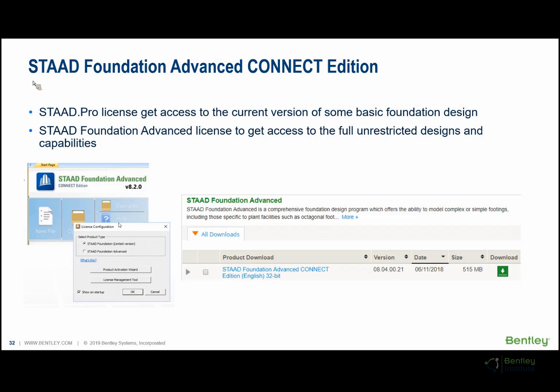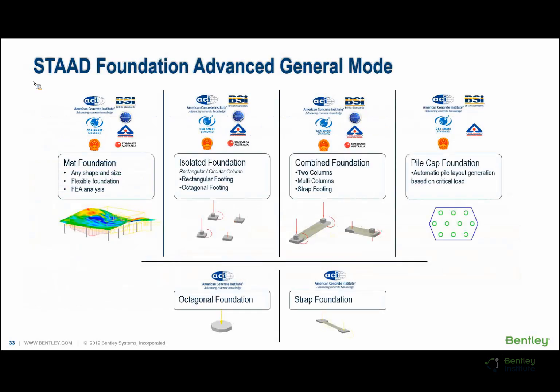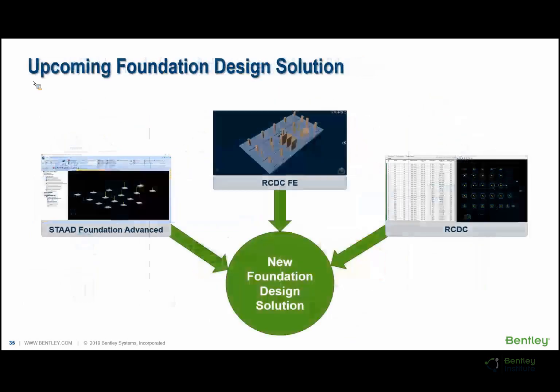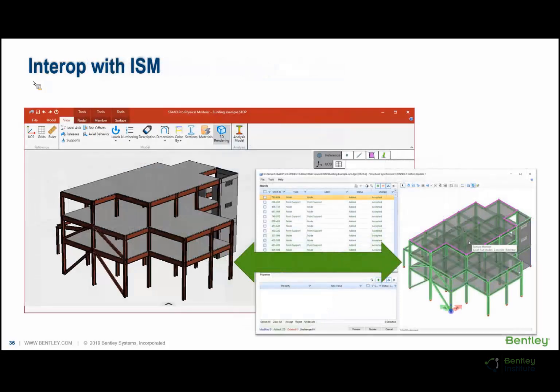If you have the STAAD.Pro license, you can do some basic foundation design like isolated, pile cap and combined footing. But if you have the STAAD Foundation Advanced license, you can do all kinds of foundation design. You can see also some upcoming foundation design solutions. I will be skipping this part, and also the interoperability with ISM.